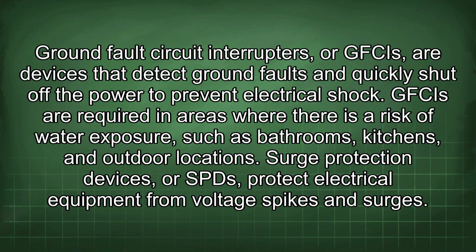Ground fault circuit interrupters, or GFCIs, are devices that detect ground faults and quickly shut off the power to prevent electrical shock. GFCIs are required in areas where there is a risk of water exposure, such as bathrooms, kitchens, and outdoor locations.